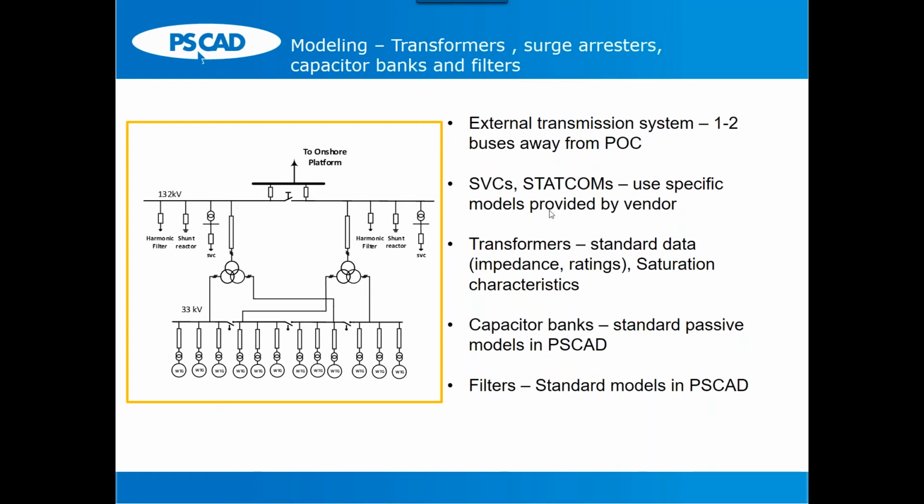So depending on your layout, if you have these elements, the recommendation is to model them or represent them using the detailed models provided by the vendor. In terms of transformers, you can use the standard models in PSCAD with standard data: the ratings, voltage, MVA, transformer impedance.